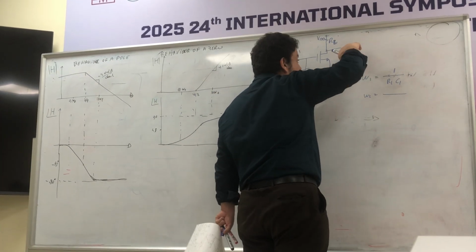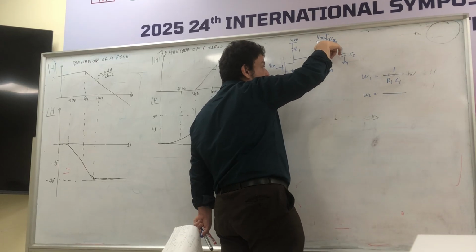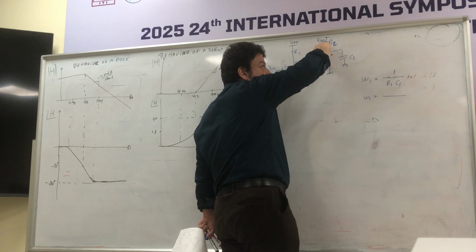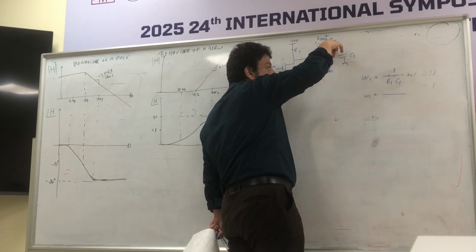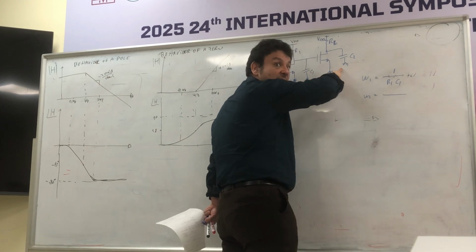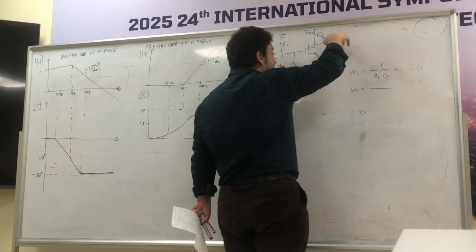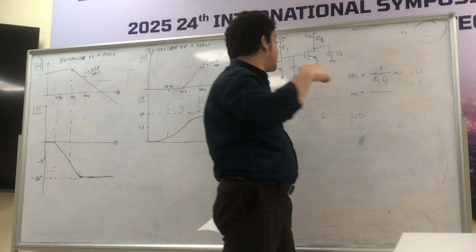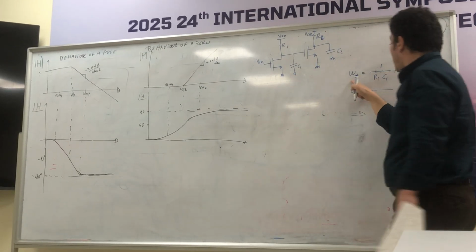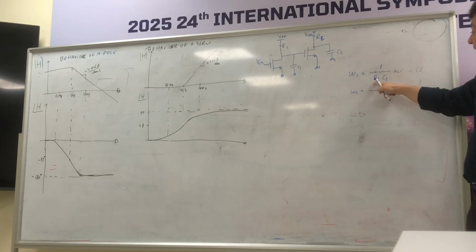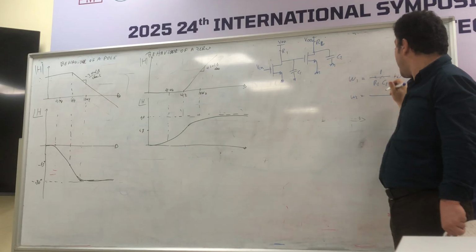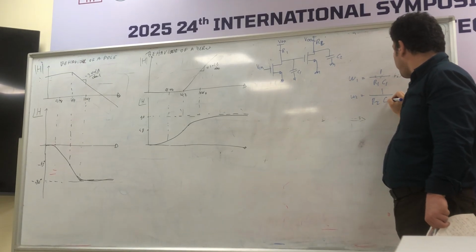I consider the resistance at the same node. Here I have no capacitance across nodes, just capacitance between a node and ground. So I just look at the capacitance. Each of them gives me a pole. Then I consider the resistance insisting on that capacitance, C1 in stage 1. So I have the respective pole 1 over R1 C1, and omega 2 is equal to 1 over R2 C2.